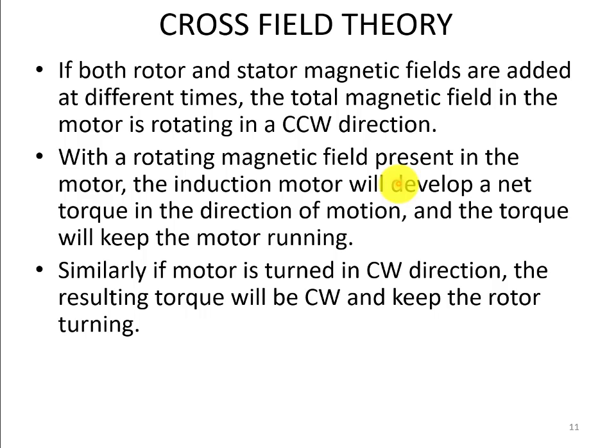To summarize what we have seen in this video: we know that the induction motor is not self-starting. It has no starting torque. We have just seen what happens if we supply a single-phase voltage to this single-phase induction motor. If it is in a stall position, it will not move at all, because it has no starting torque.